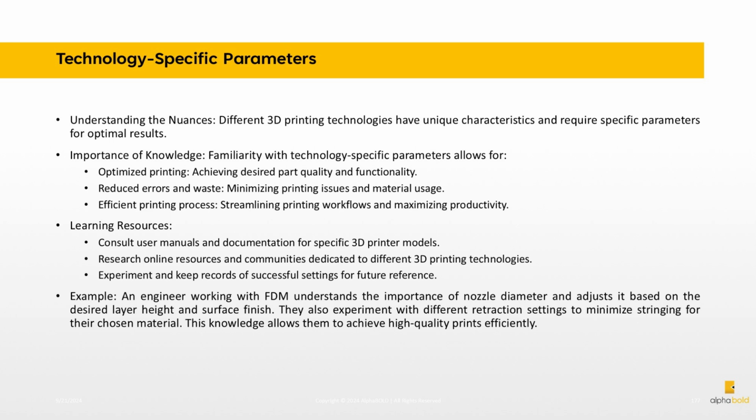Example. An engineer working with FDM understands the importance of nozzle diameter and adjusts it based on the desired layer height and surface finish. They also experiment with different retraction settings to minimize stringing for their chosen material. This knowledge allows them to achieve high-quality prints efficiently.